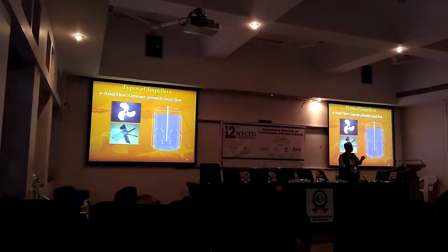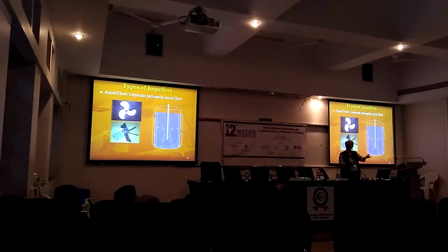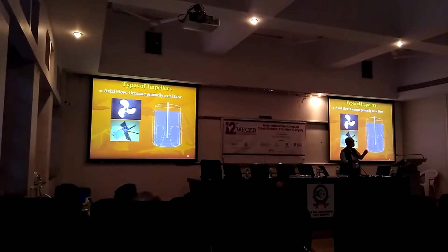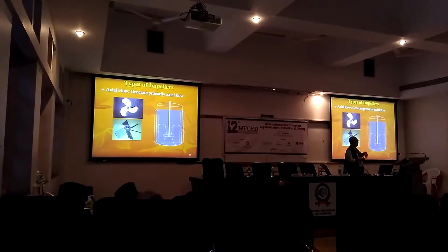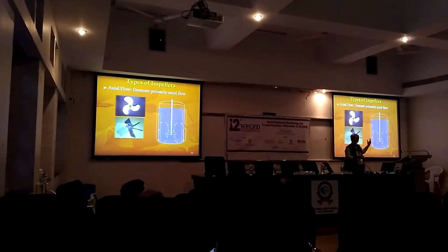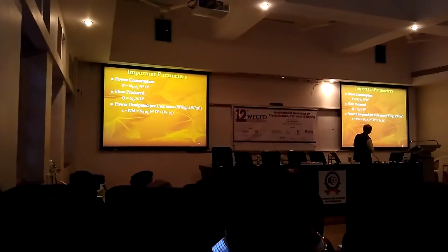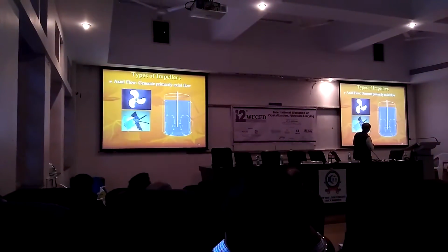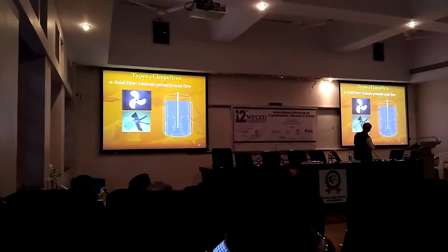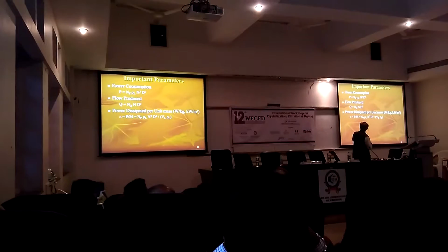As a result of which you use axial flow impellers, which create a very high flow but very low shear, as a result of which the crystals are protected and you are in a position to achieve, because of the high velocities, a reasonable value of heat transfer coefficient as is the requirement. So this is the axial flow impeller which creates a single circulatory flow pattern, and then you need to estimate